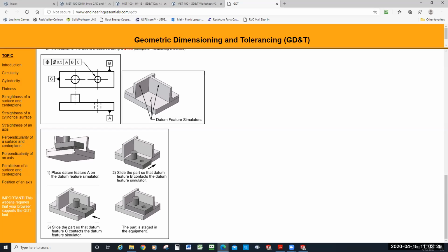Yeah, that can still tilt left or right, even though you've got it butted up in there. It still could be not flat. It could tilt this way, is the way I look at it. Yeah, and that's going to throw off your dimensions. Right. It'll move the center of those points.